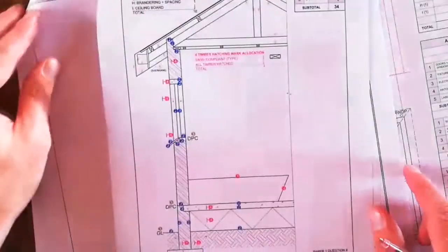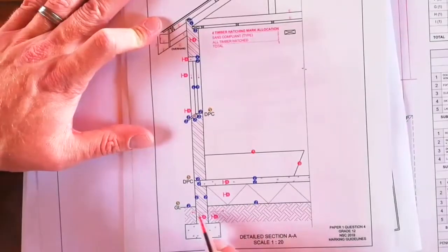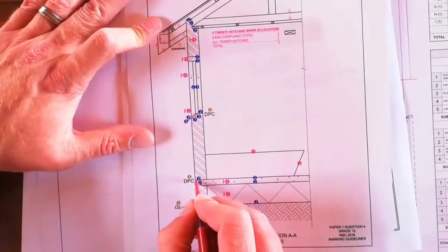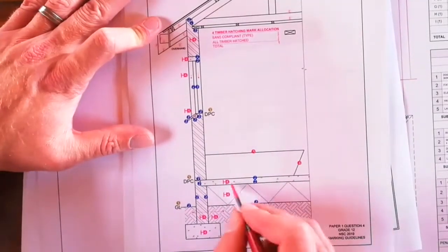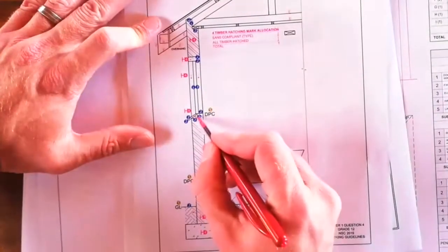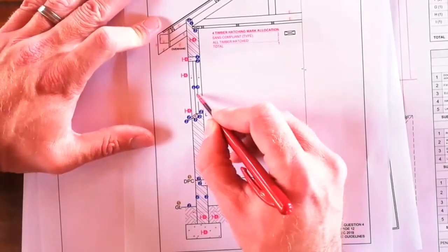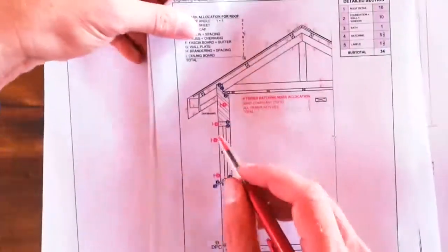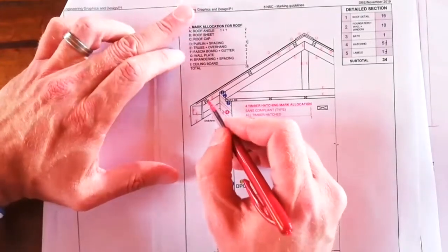Let me show you just the answer here for that section. This is the actual memorandum, so you can see how this works. Make sure you get your hatching right. You have your wall hatching. They're looking to see the line of the damp-proof course. Make sure you indicate that natural ground level. Your compacted fill concrete. There's the bath. Remember, that's a symbol for a bath. It's a side view. There's your window. We want to see the concrete fill underneath the window sill. We want to see these two lines in the center of the window. We want to see the lintel. And yes, here we go. The actual purlins.